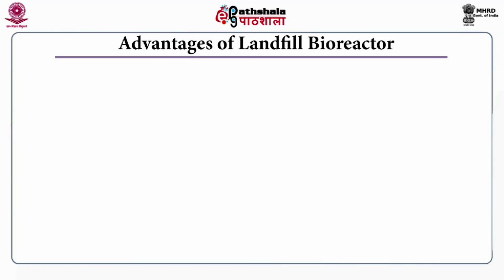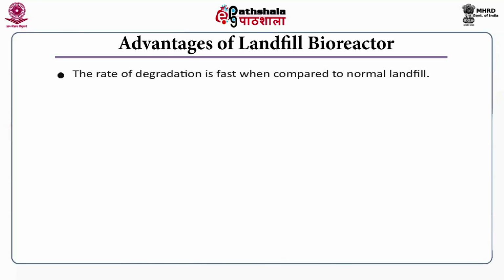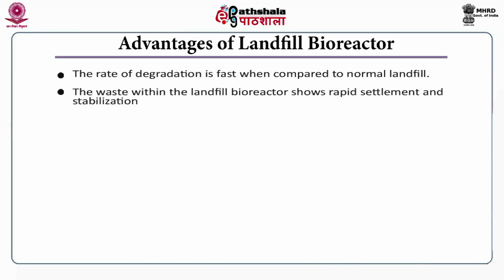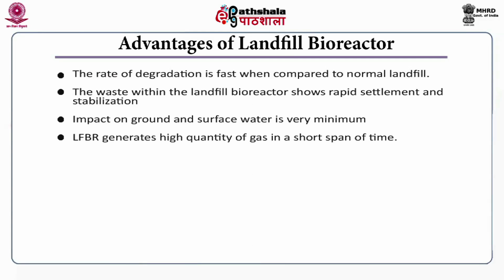Now, let us look into the advantages and disadvantages of a landfill bioreactor. The rate of degradation is faster in a landfill bioreactor than in a conventional landfill, and that becomes a major advantage. The waste within the landfill bioreactor shows rapid settlement and stabilization. The impact on the ground and surface water is very minimal, and they generate a very high quantity of gas in a short period of time, which is again a major advantage. The greenhouse gas emissions are generally reduced, which is again one of the major advantages of a landfill bioreactor.